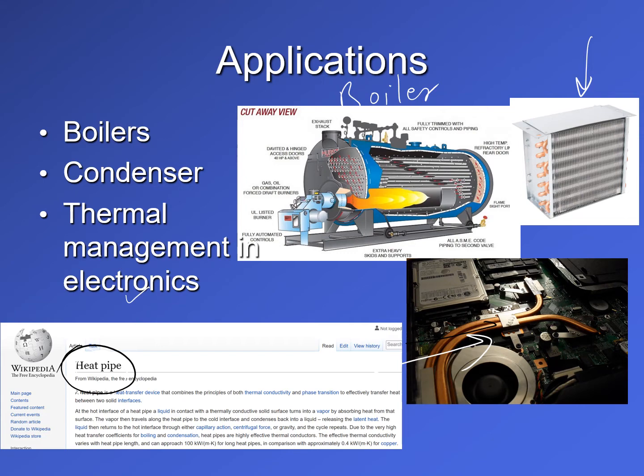So the liquid which is contacting the hot surface will result in a phase change, so it will extract a large amount of heat because it will change its phase into a vapor, and this vapor then again will be condensed later, and that will result in this vapor giving a large amount of energy to some cold surface, and again convert to liquid, and this process will continue in these heat pipes, resulting in a large amount of heat transfer and allowing thermal management of electronic components which can get really hot because of the high power they deliver these days.